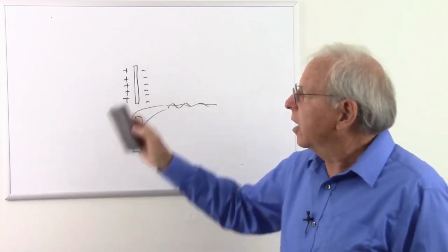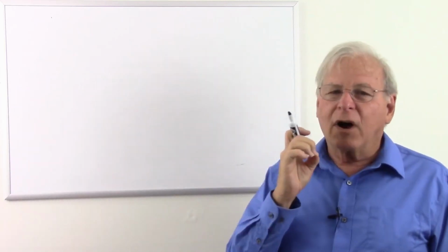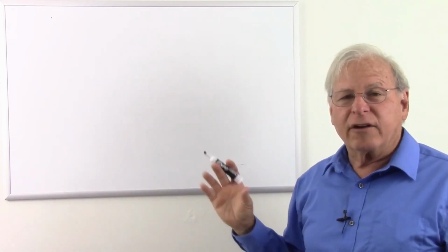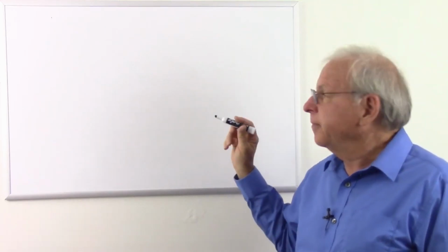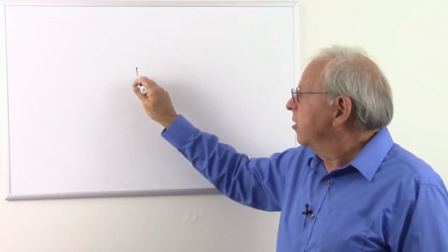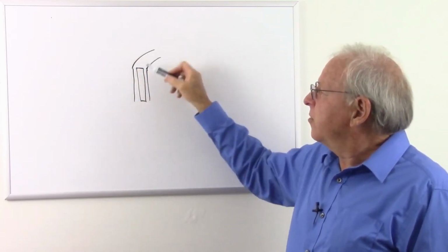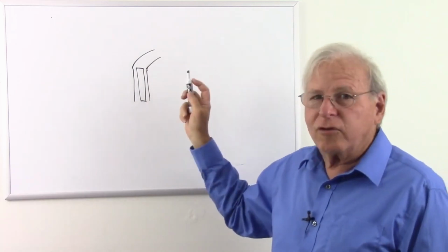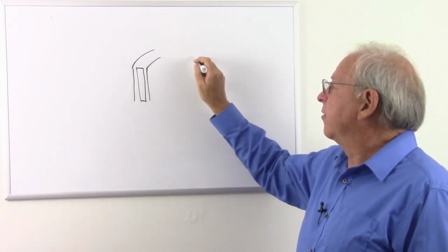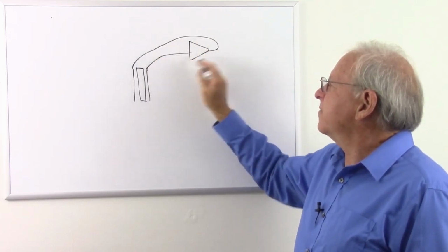Another way this is exploited is in radio circuits, not necessarily radio circuits, but in oscillators that are often used in radios. We have a crystal. Here's a picture of the inside of one here. You can see the crystal with the plates on it. And what that does is if you put alternating current across that crystal, so I'll draw it again here with the two plates. If we put some alternating current across there, that crystal wants to vibrate at a very precise frequency. And so if we run this to an oscillator, I'm just going to show that as a simple symbol. I'm going to show it kind of feeding back to itself here.